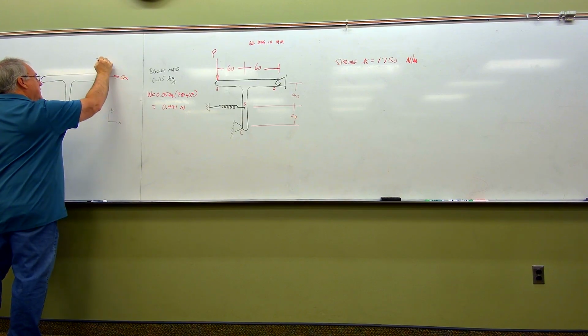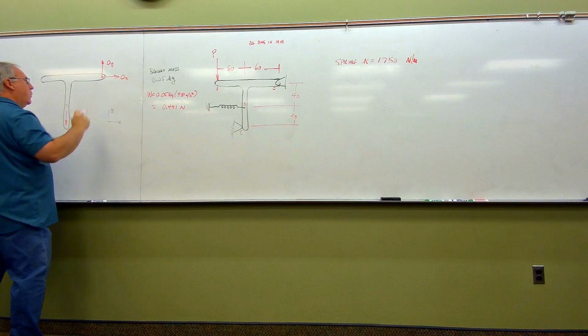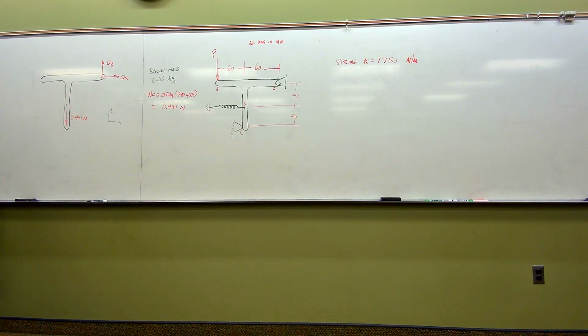I'm going to call it OX. Maybe I got some Y directional force right here, I'll call it OY. Again, folks, I hope you're all getting to this point here. When you see a pin, just right off the bat, you just think, hey, X force, Y force. It's really that simple, unless, again, you see a 2-force member. But as we talked about in the previous one, 2-force members can't have any weight, so it's automatically out. This is not a 2-force member.